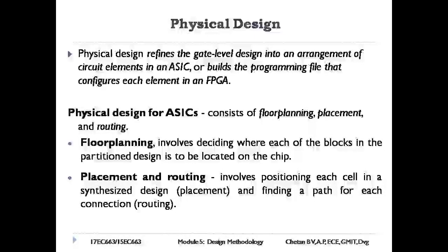It also covers the connection and distribution of the clock across the chip, and provision of channels for laying out interconnections between blocks. EDA tools can assist to visualize floor plans and rearrange blocks, ensuring all the time that a floor plan is feasible, and by analyzing alternative floor plans to determine figures of merit.